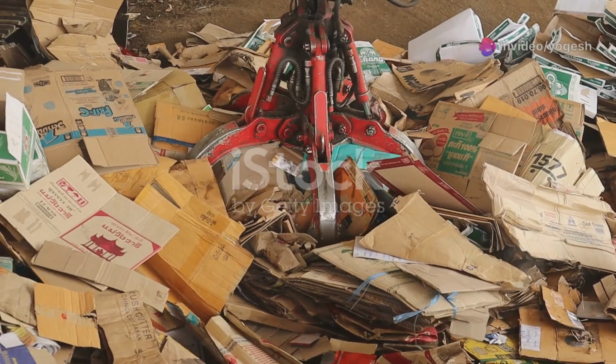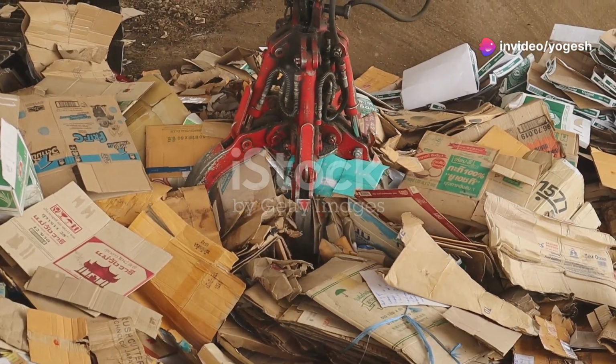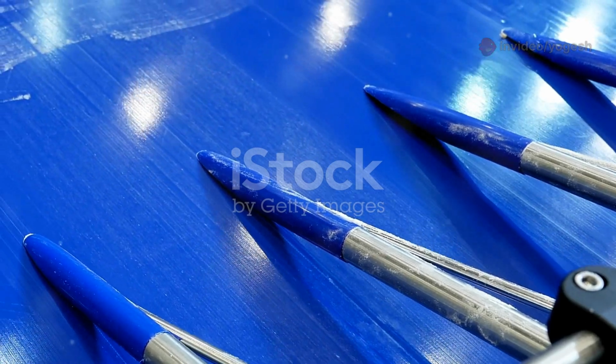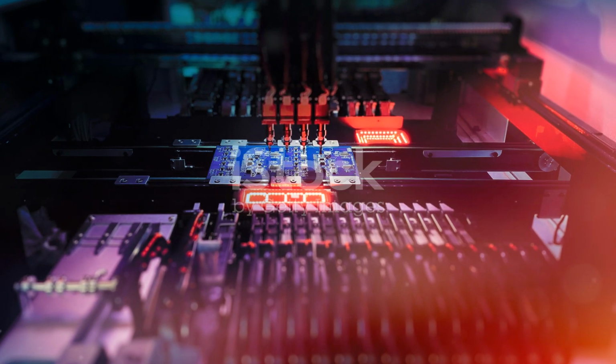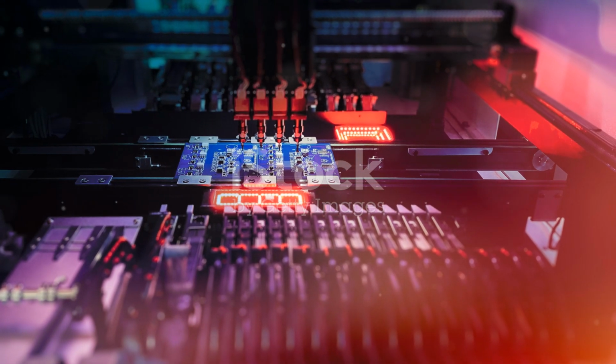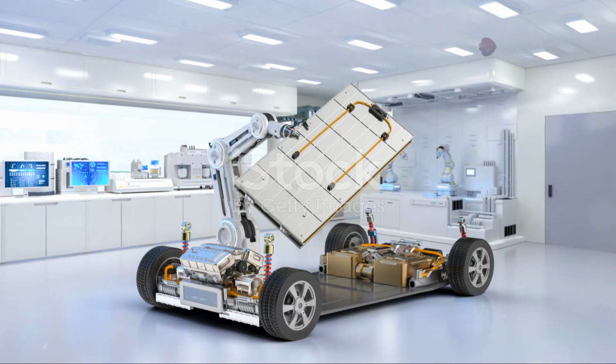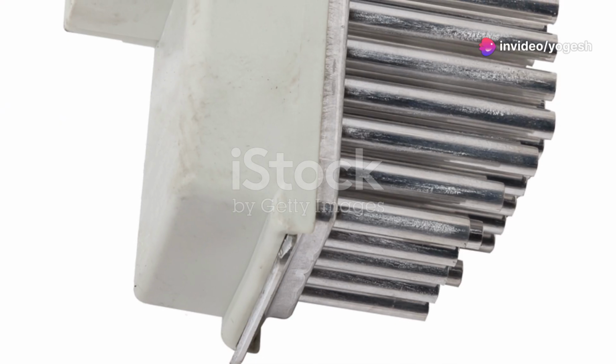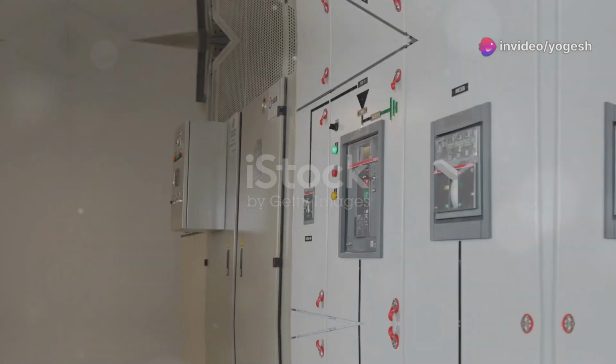I corrects for any droop or steady error due to gravity. D smooths out the motion, preventing jerky movements or vibrations. This allows robots to perform delicate tasks with amazing accuracy. Automotive engineering also relies heavily on PID. We have already talked about cruise control.